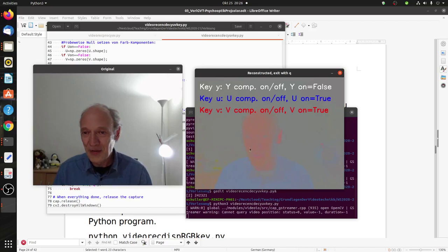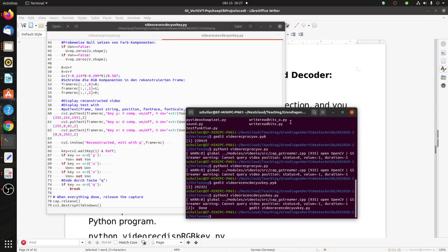Yeah, so basically this shows why this transform is so useful, right? By just looking at U and V, we can see that we can reduce the resolution without the eye noticing it. So that allows us to save a lot of transmission bandwidth or number of pixels transmitted. Right? So this is why this reduction of transmission bandwidth to 1.3 megahertz works compared to the 5 megahertz for the Y component.